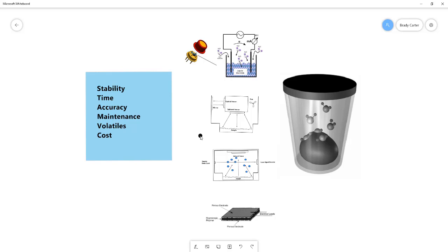And so the maintenance requirements that are needed to maintain that accuracy are fairly high, as opposed to the electrolytic sensor, which also has a high accuracy. But because the sensor is protected, it's not nearly as susceptible to cleanliness issues. And so the accuracy that it's reported can be maintained much easier without having to have so many times of cleaning or so frequent a verification or making calibration adjustments.